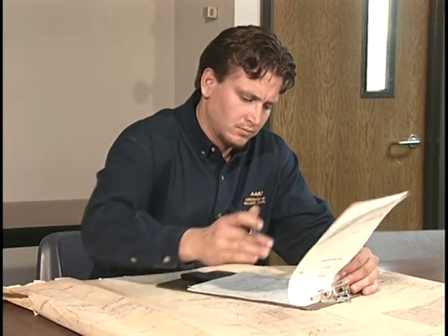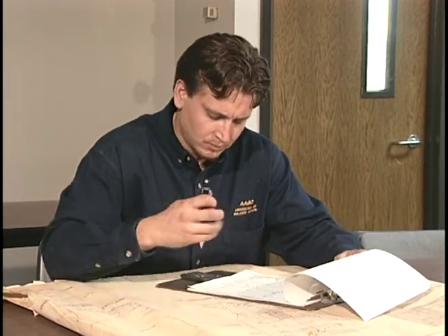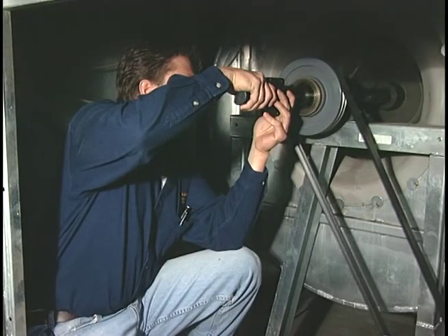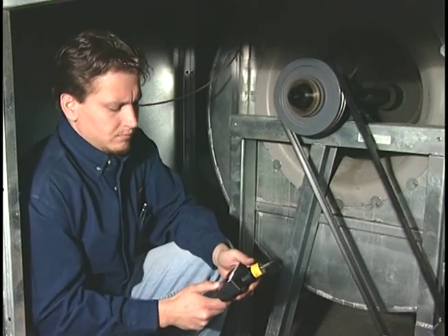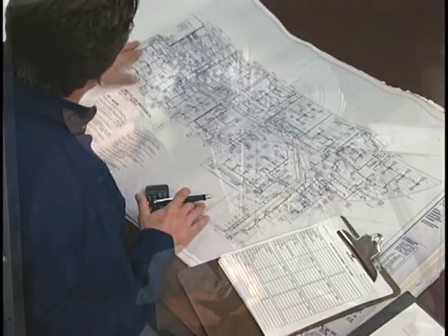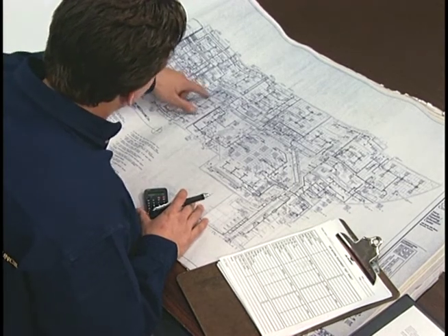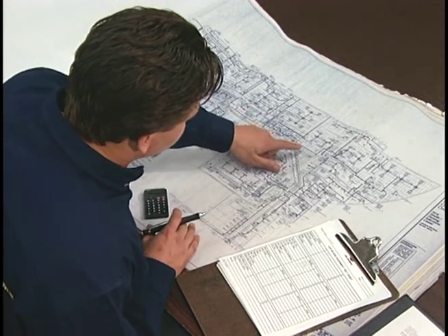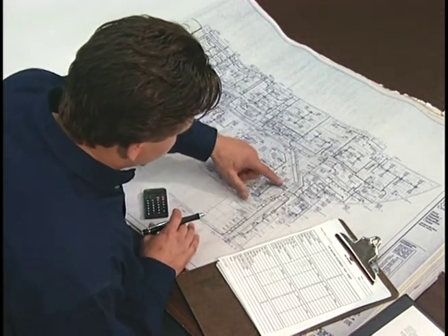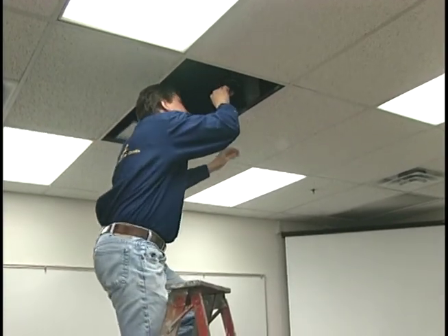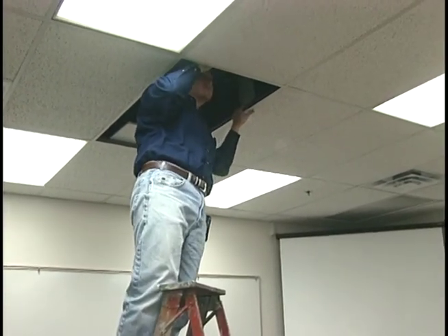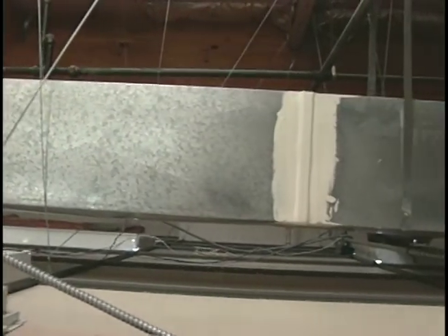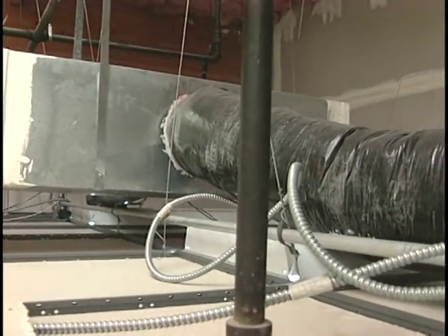To balance a single-zone system, the TAB technician first reviews the prints, completes the preliminary data sheets, and sets up the fan and duct system for balancing as outlined in previous training videos. While still in the office, the technician selects tentative locations for pitot tube traverses in the main duct, return air duct, outside air duct, and all branch ducts. Then, during the site inspection, the technician confirms that these locations fit the criteria for taking an accurate traverse. If they do not, the technician selects new locations.